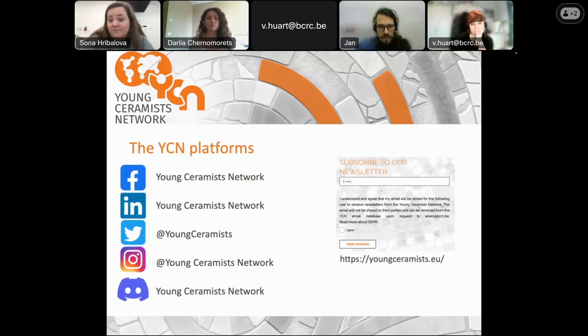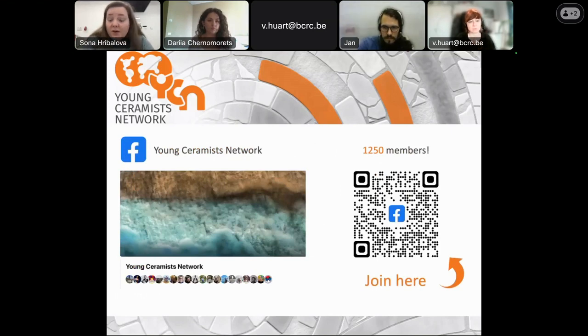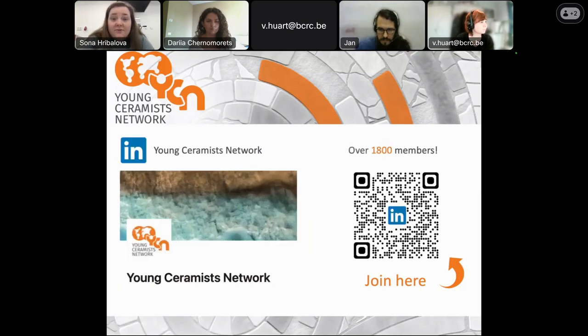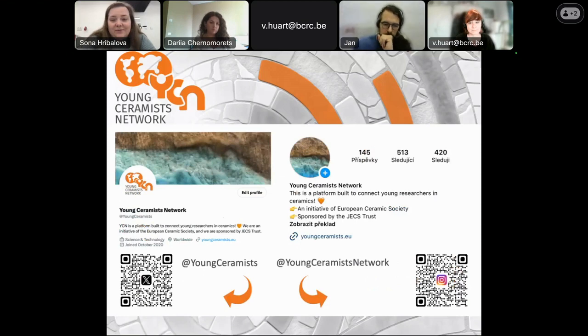Because then there's also absorption. If you have any colored piece of glass, it's going to absorb part of the spectrum. So that's something everyone is pretty much familiar with. And of course, the thicker it gets, the more it gets absorbed. And so you have actually less light passing, at least at a certain wavelength. But again, this depends on the composition of the material. So if you know the composition of your material, you're pretty much able to define, regarding reflection and absorption, if it will get transparent. But that's not all, unfortunately.